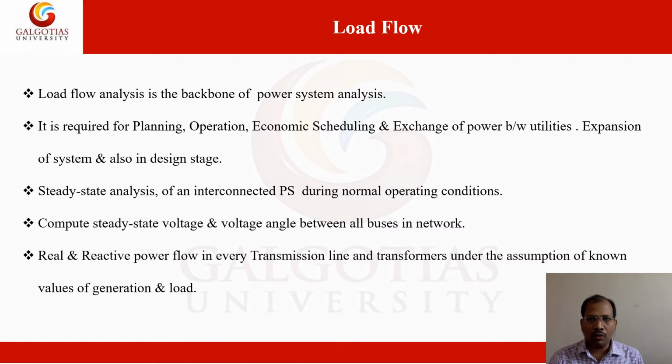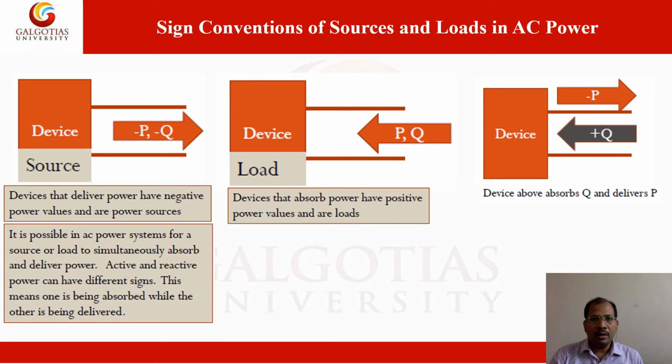So this is our objective, and using these phasor voltage values we also have to calculate the real and reactive power flow in every transmission line and transformer, under the assumption of known values of generation and load. We can also calculate the loading condition of a particular transmission line and the status of the circuit breakers. So these are the basic concepts we are covering.